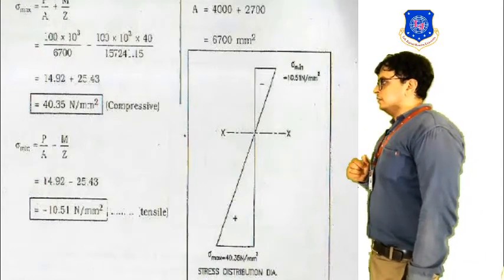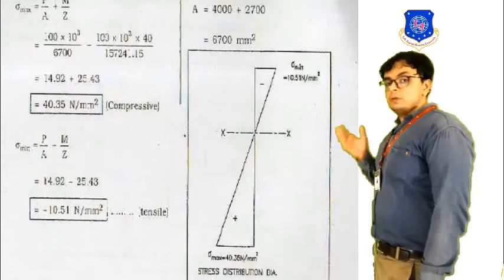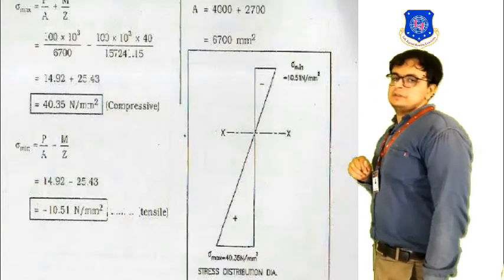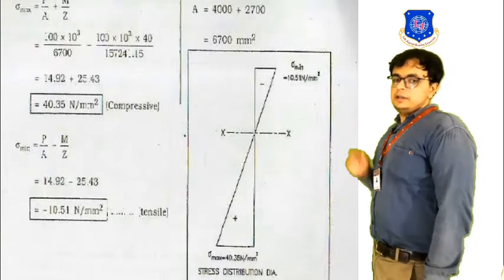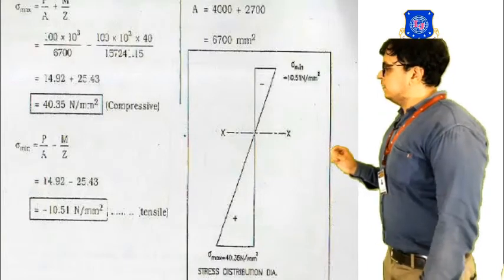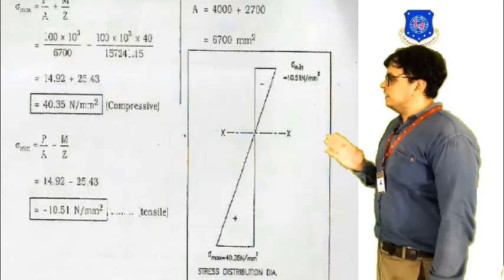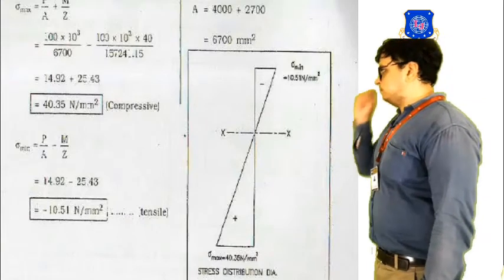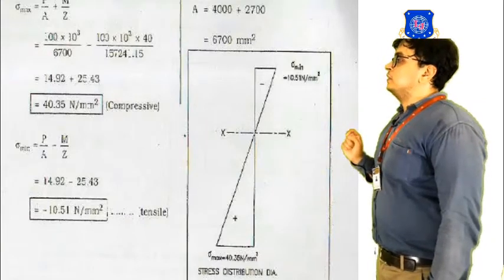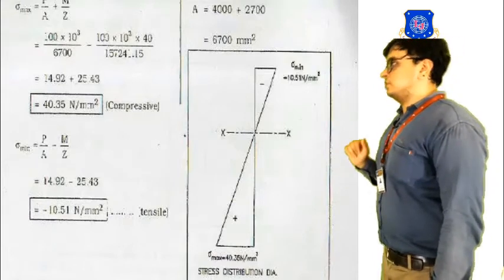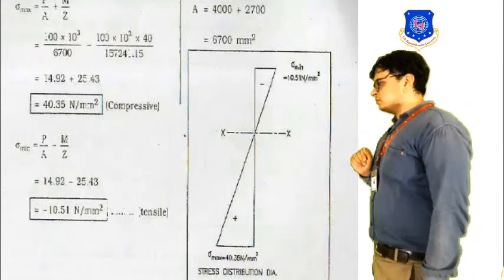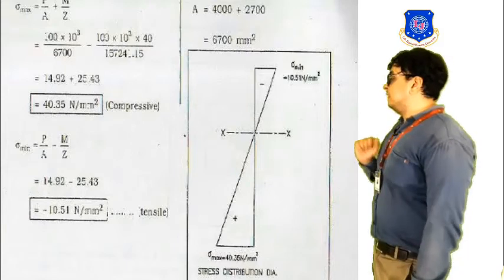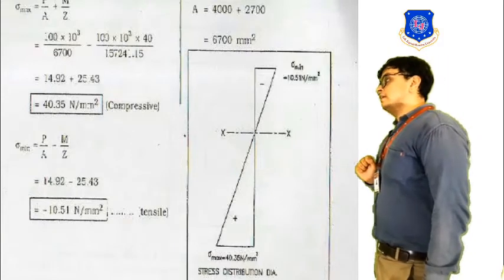Okay, and it is acting at the bottom because it is positive, and it will start from the bottom, and slowly when we move towards the top we will get the tension. You can see over here that initially it has a rectangle moving on the left hand side, and slowly it moves towards the neutral axis, and a point will come where it changes its characteristics from compression to tension. So slowly moving towards the top, at some height its characteristics change, and finally at the topmost section we get the tension.